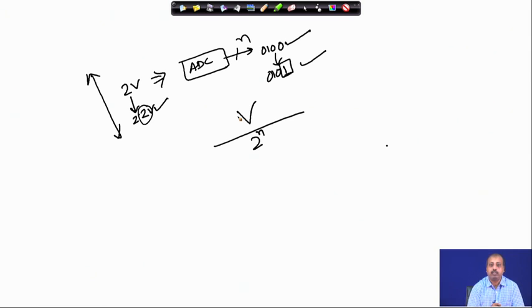It is not that, say V equal to 5 volt, for 0 to 1 volt it produces values which are close to each other, and from 4 to 5 volt it produces values which are far away from each other. The corresponding change in the input voltage that is required to change the LSB would then be different over different ranges of voltage value. We are not really happy with that situation, because then this conversion does not have much reliability. So, ideally I would like to have a system where this range is uniform, so each of them is converted into proper values within the range.